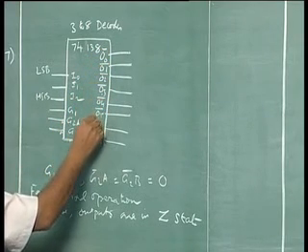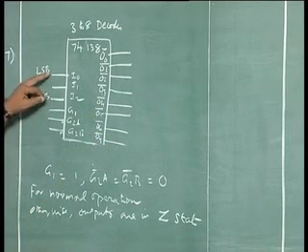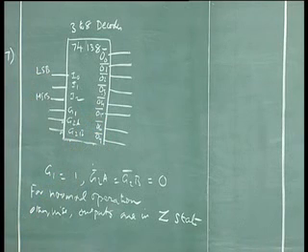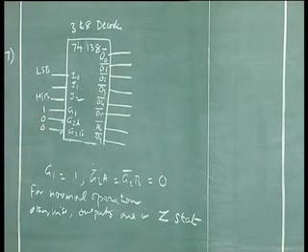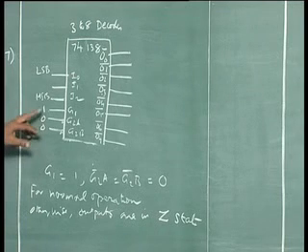That means if a particular combination occurs after enable is properly connected, of course. So assuming this is 1, this is 0, this is 0, I have properly connected the enables. If this is the only circuit in my IC and it's not being required to be controlled by any other event in the circuitry, I can directly connect it to ground and power supply.